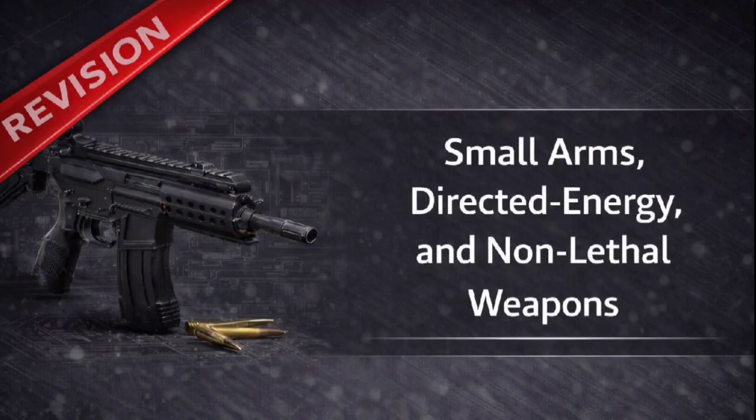Let's expand on that. How do tiny, invisible variances in ammunition translate into dispersion downrange? Well, manufacturing variances in ammunition are a primary cause of inconsistency. Subtle differences in the propellant load or the weight of the bullet lead directly to variance in muzzle velocity. And if the velocity isn't consistent, the trajectory changes. This causes significant dispersion downrange.